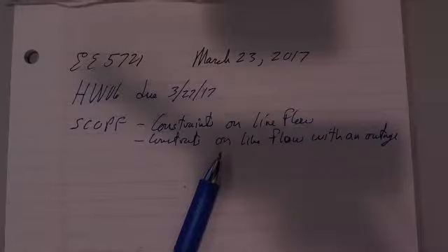This is the way markets operate. If you just do economic dispatch, you get the least cost. If you put line flows in there, the economic dispatch might overload some lines. It shouldn't, because you probably didn't do a good job designing the transmission system.